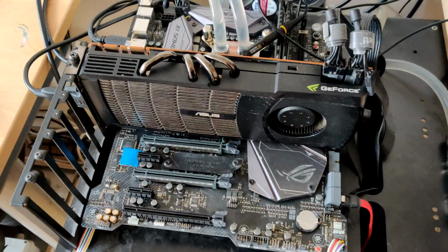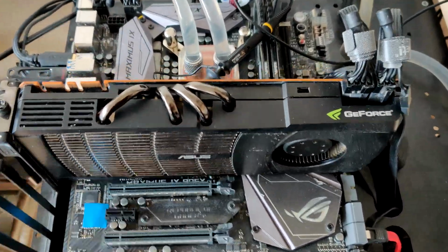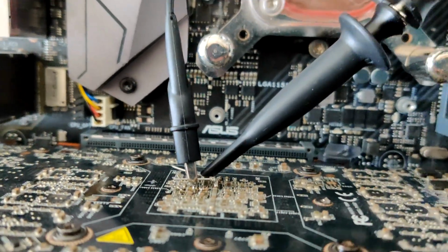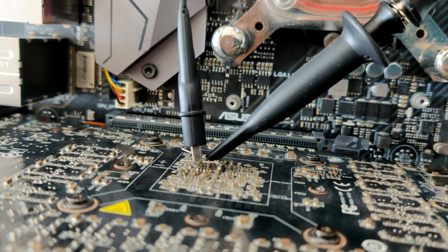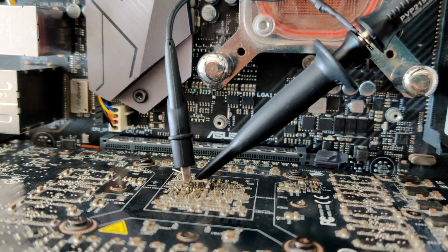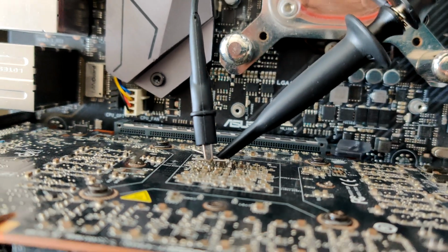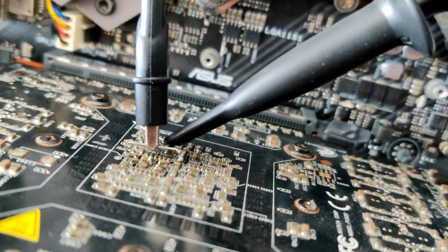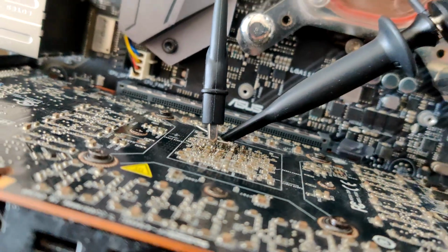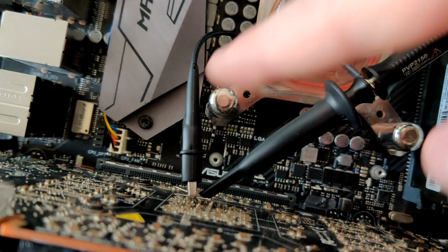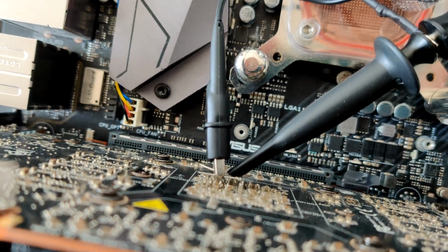Now, as to what we're going to do, here is a reference GTX 480, and I have hooked up the probe to the back of it. Now, this way of attaching it is not good. I will try to get a better thing done. Many people have been suggesting to buy a BNC cable, cut it, and then have a proper hookup soldered to a multilayer ceramic behind the card right here, because using a regular probe, especially this ground alligator clip right here, can really screw with your results.